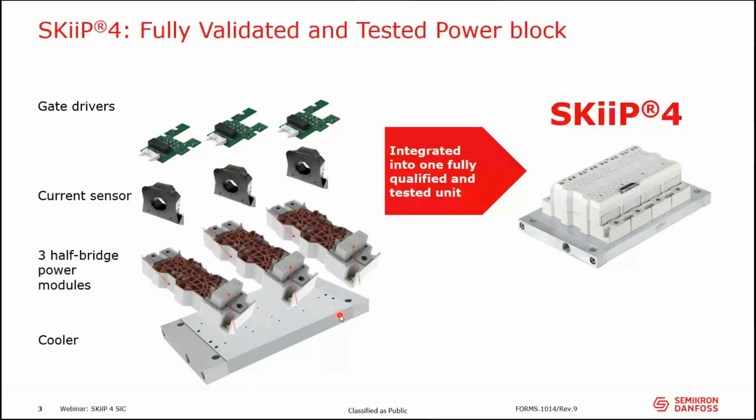The heatsink can be water, air, or customized heatsink, depending on the application we are talking about. And last but not least, the driver is also part of the assembly, including protection functions: over current, over temperature, and over voltage protection. This all designed, qualified, and then assembled and end-of-life tested is then a SKiiP assembly, SKiiP IPM, Intelligent Power Module.